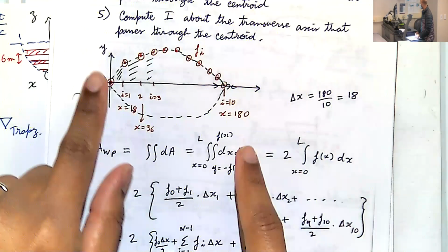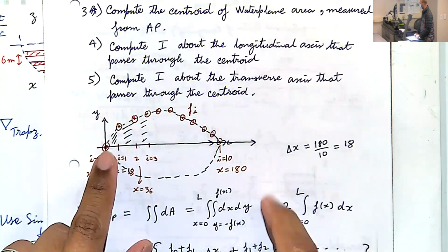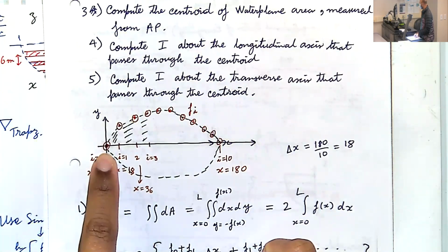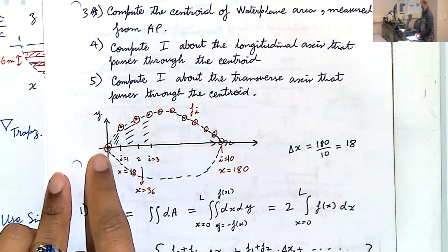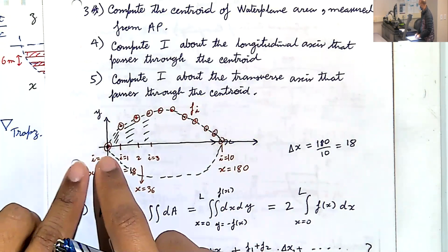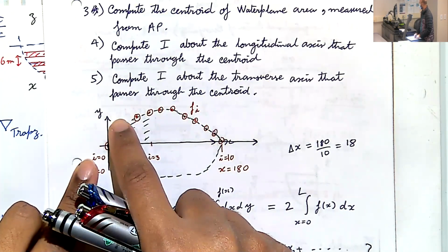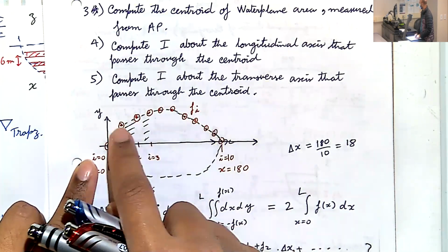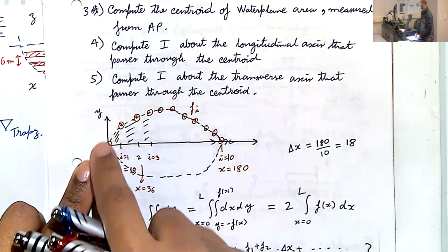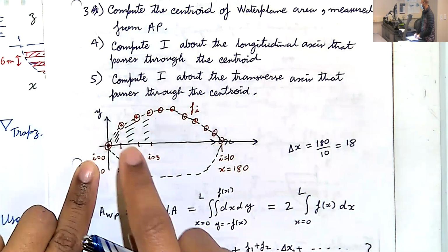But it doesn't. Remember, that's exactly what we did in the previous class. All the computer needs is, at this coordinate, this again is the top view of the water plane, what's the lateral distance to my hull from the center line? And once you know that for all the different points, you can compute the area numerically. So that's exactly what the computer does.